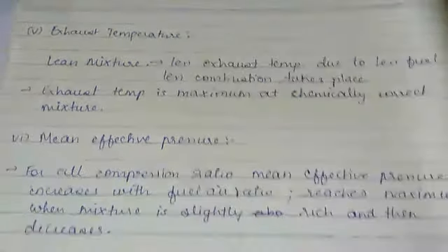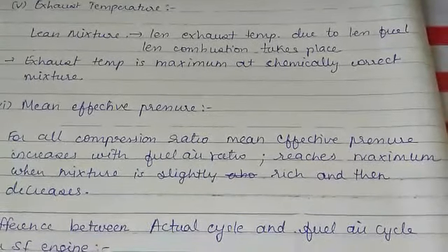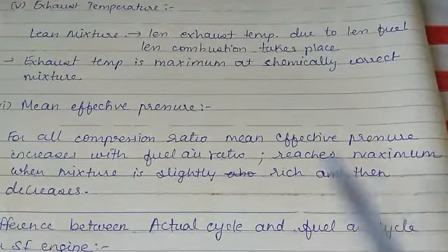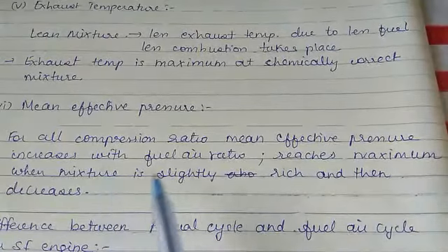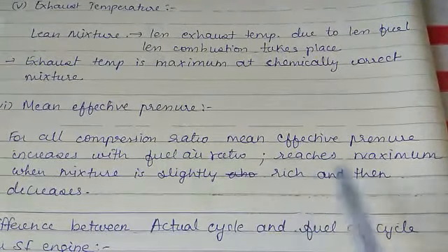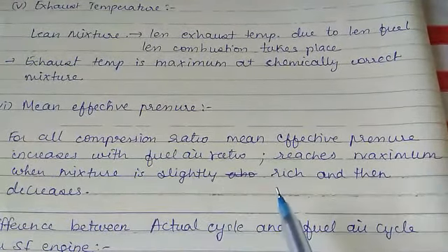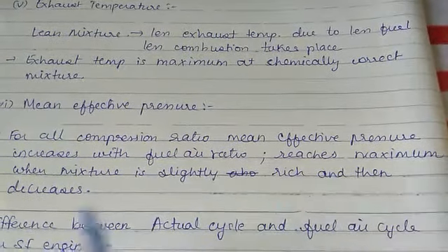Next point, mean effective pressure. For all compression ratios, the mean effective pressure increases with the fuel air ratio, reaches a maximum when the mixture is slightly above rich, and then decreases.